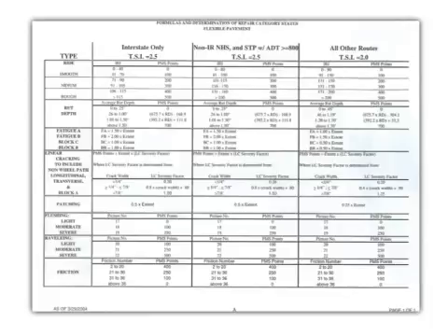We give certain points for every distress, extent, and severity, and eventually these numbers are going to be subtracted from one single grand number, to have an overall pavement condition index.